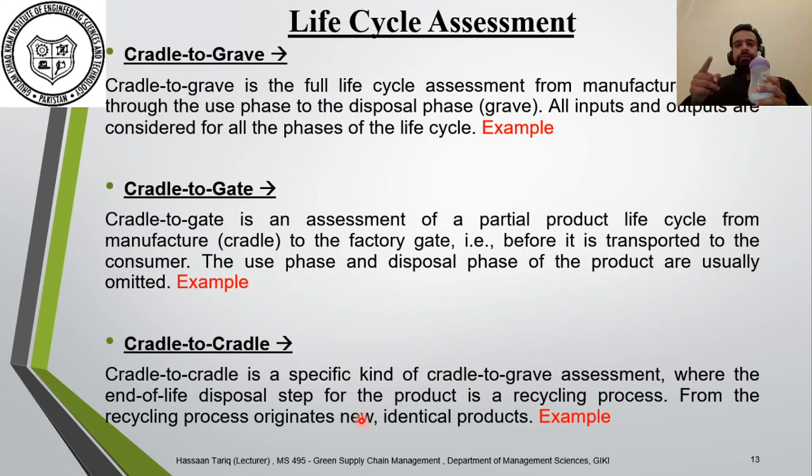So basically, the energy consumption or the emissions that have been used for making that polypropylene or polyethylene into its genuine form is further accumulated into my life cycle assessment calculations, apart from the ones that were in cradle to grave. So cradle to grave plus recycling, that is cradle to cradle.